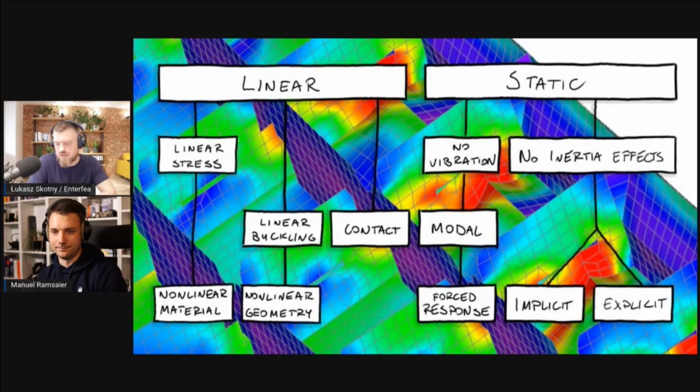Because what people get really wrongly is that linear buckling is not the capacity. When the linear buckling says, you need to increase your load multiplying with 1.2 critical multiplier, everybody thinks, I have 20% of capacity safety, extra. This is not how it works. Because what you actually get is in ideal world, when nothing wrong can happen, everything is perfect geometry.